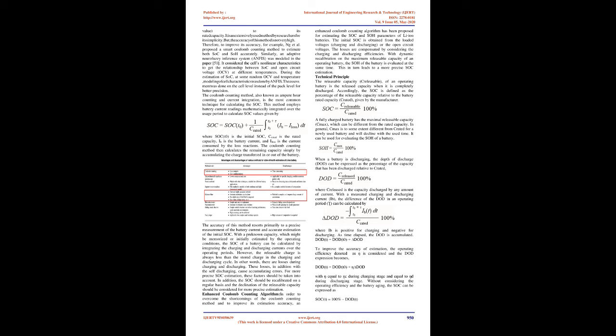Kalman filtering is a promising alternative approach that circumvents these challenges with a slightly higher computational effort. Such observers typically include a nonlinear battery model, which uses the current and voltage measured from the cell as inputs, as well as a recursive algorithm that calculates the internal states of the system, including state of charge. However, estimating the SOC for modern battery chemistries that have flat SOC discharge signatures requires a different approach. Extended Kalman filtering, EKF, is one such approach that has been shown to provide accurate results for a reasonable computational effort.